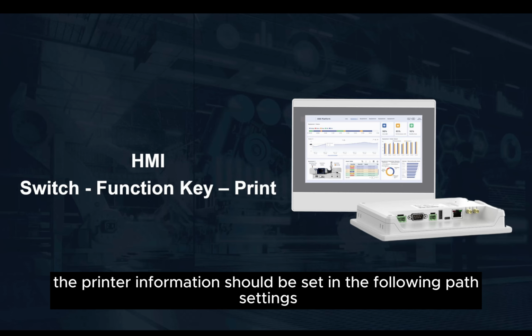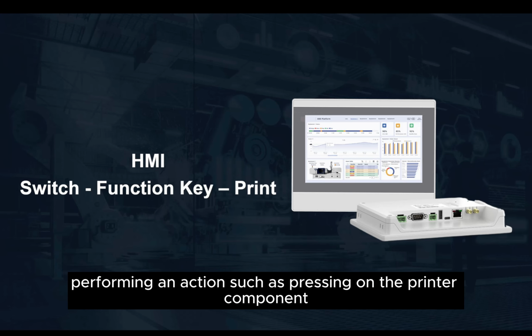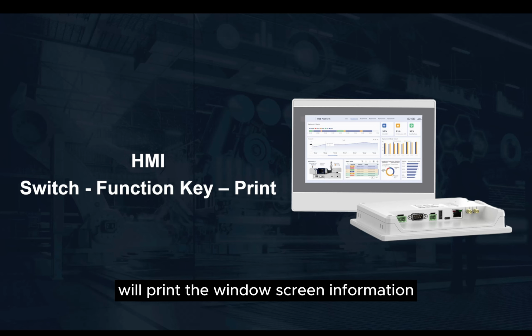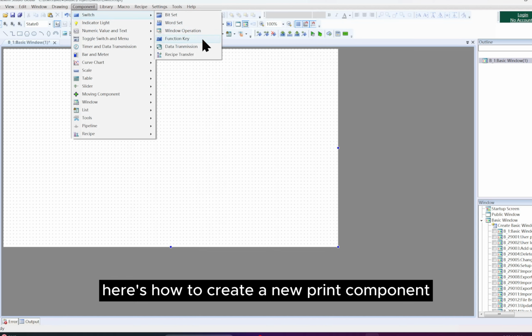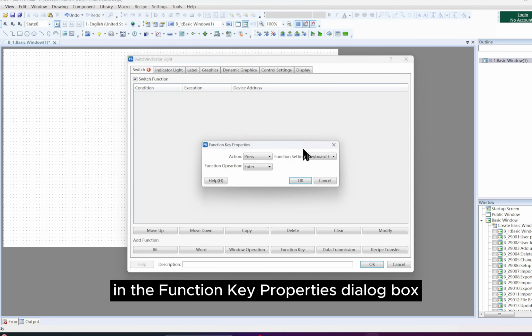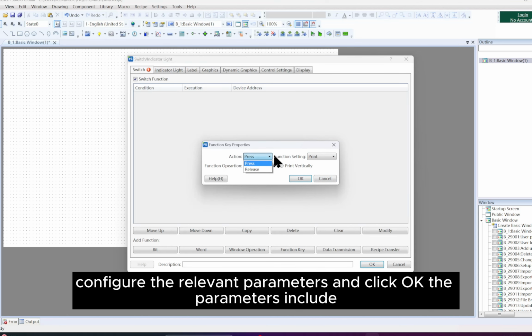The printer information should be set in the following path: Settings, Communication Settings, Printer Interface. Performing an action, such as pressing, on the printer component will print the window screen information. Here's how to create a new print component. In the Function Key Properties dialog box, set the function setting to Print, configure the relevant parameters, and click OK.